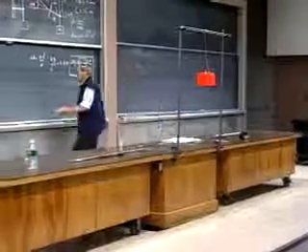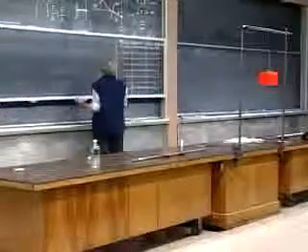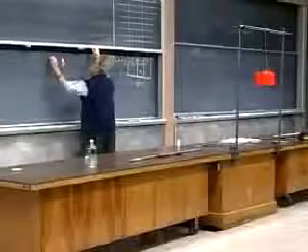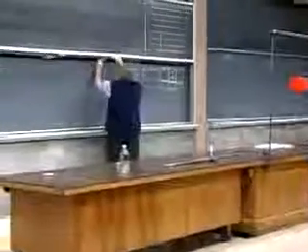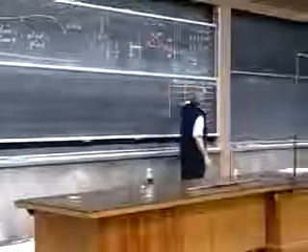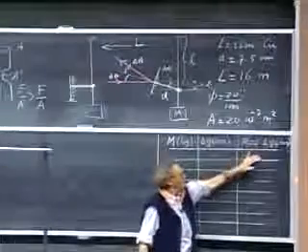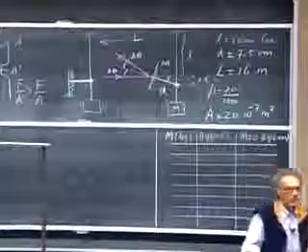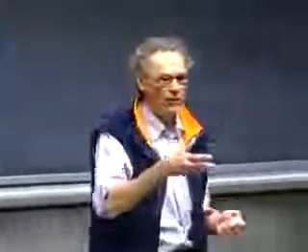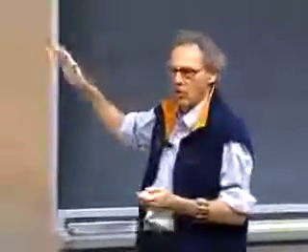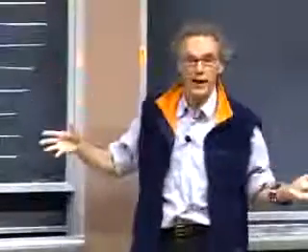So I will now make an attempt to load down the copper wire. Oh, we can actually leave this here, so you can see that curve. So we start here, we go up with 0.5 kilograms. We will write down then how much that laser spot goes up on the wall. And then in between increasing the weight, increasing the force, we will take the masses off to see whether the length of the rod returns to the original length. And you will see after a while that you get permanent deformation, then it no longer comes back to its original length. In other words, the laser spot will not return to 0 on the wall, but it will stay higher.